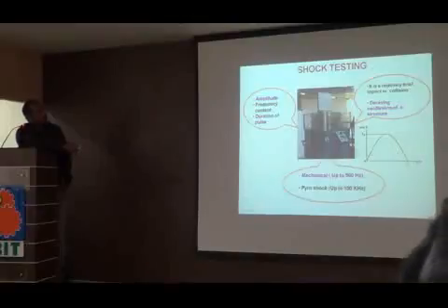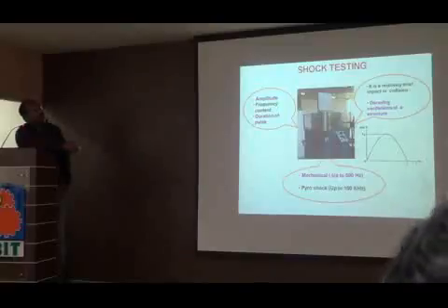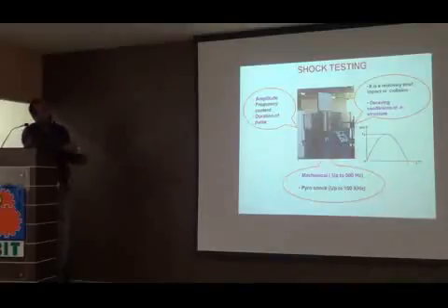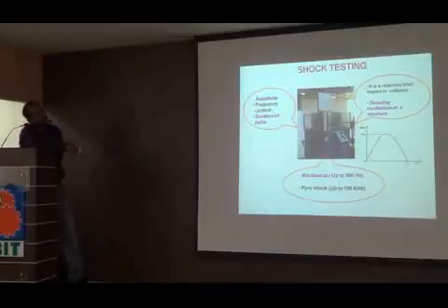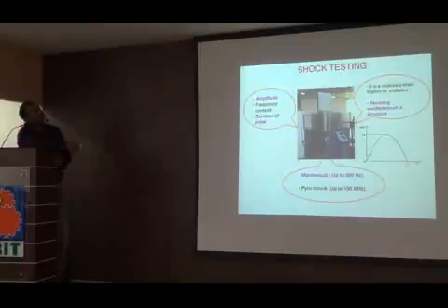Most of the shocks can be mechanical or pyro shocks. There are two types. What we call mechanical is up to 500 Hz, because of low frequency. Pyro shock is due to pyro firing. It can be very high frequency and high amplitude shocks. These can be generated in a laboratory, but they have some limitations. It either has to be generated by burning the actual pyros, meaning the actual detonators, or some kind of testing can be done. But this is what we do mostly: we convert these kinds of shocks into this by some kind of studies, and then simulate these to study the structures.